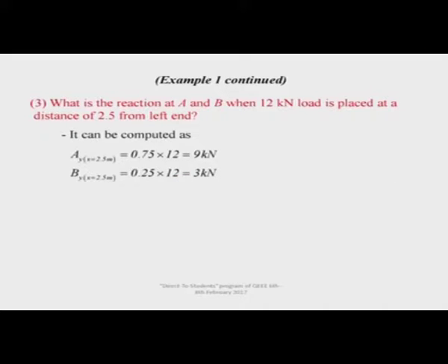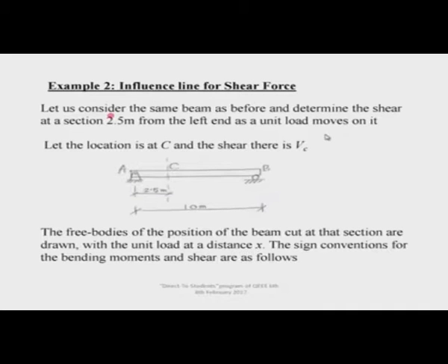It may appear to you that there is no need for an influence line diagram, that I can find it from statics. Yes, this example is preliminary, explanatory to the students, that is why it is so easy. It is meant for practical bridges where the structures are complicated, the live loads are many, they have different load paths, and you have the influence diagrams ready. So, that is how it is actually very convenient.